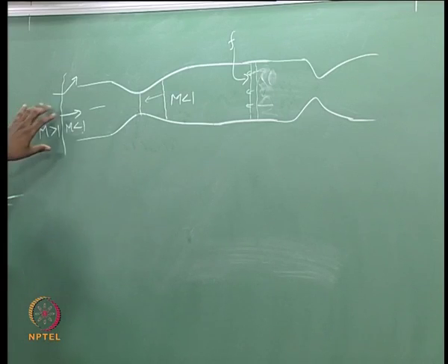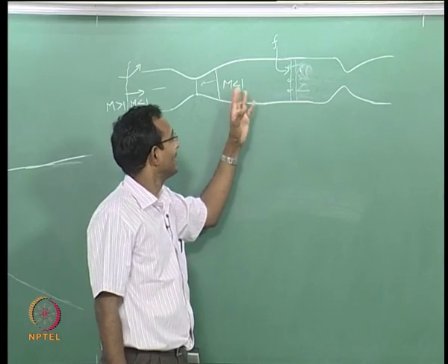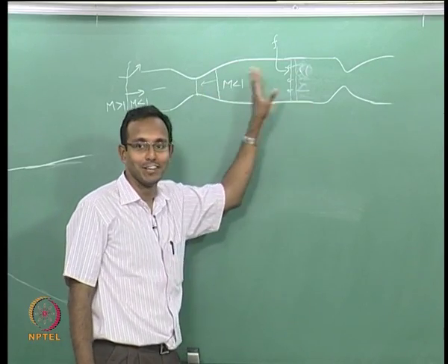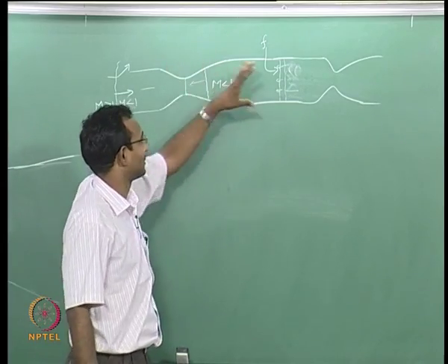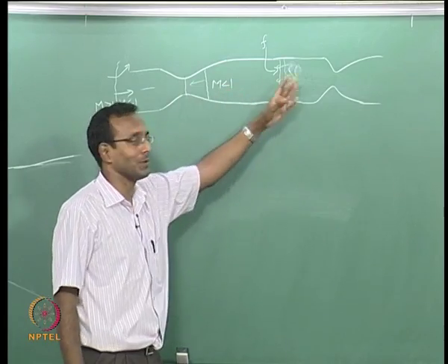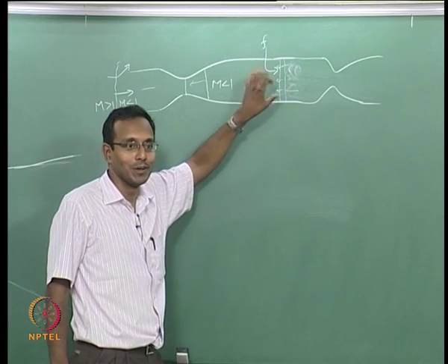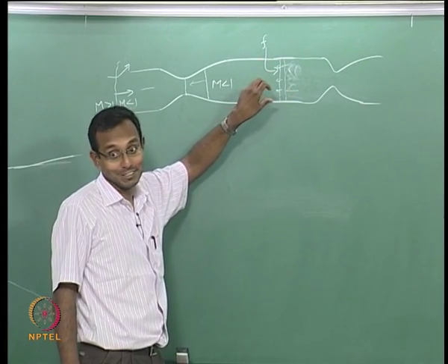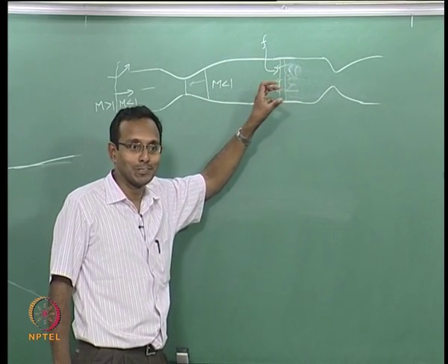So now this can start happening and added to this, if there is some pressure oscillation inside here, which is characteristic in these kind of ducts with partially closed ends, if there is a pressure pulse, it is going to be reflecting up and down inside here, and the pressure inside the system is going to be going up and down. Coupled with this, when the pressure increases, the flame burns better because molecules are closer.